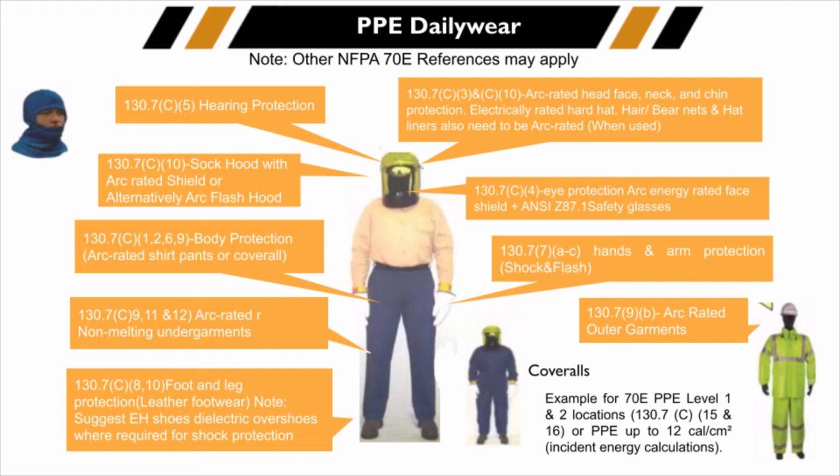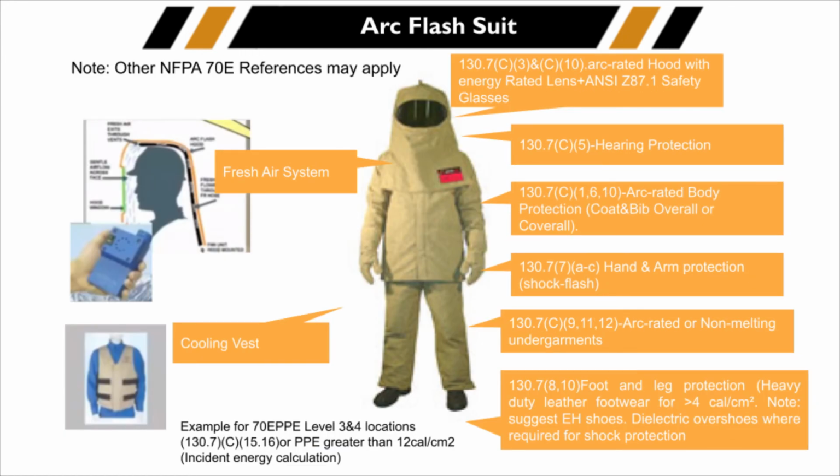They also make arc rated hairnets and beard nets. So if you have to work in an area where a hairnet or beard net is required, this is something you should look at, because hairnets and beard nets that are not arc rated can burn and melt very easily.